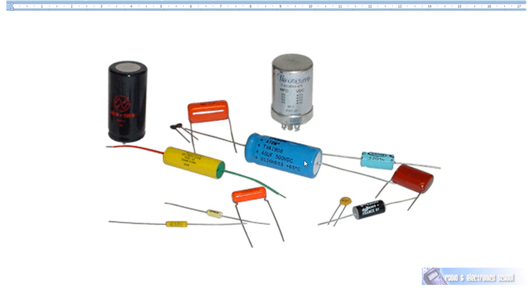Also, if you put the voltage the right way around but you exceed this 500 volts DC, the capacitor will explode. Particularly when they're reverse connected, they can make quite a bit of mess, because all that paste I spoke about would end up all over the radio.